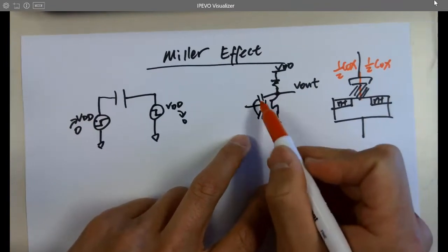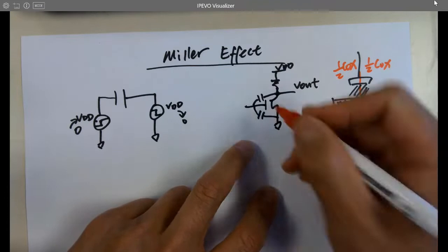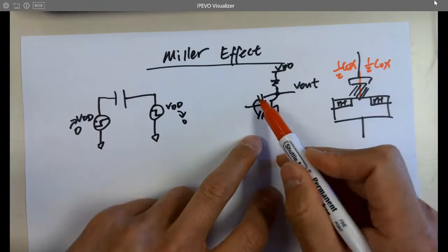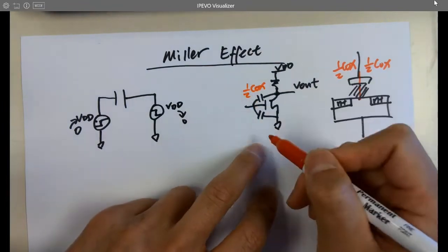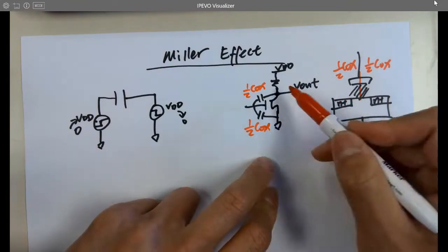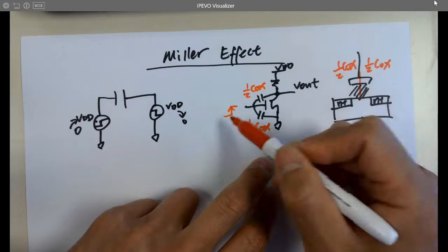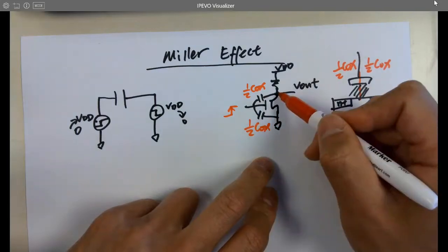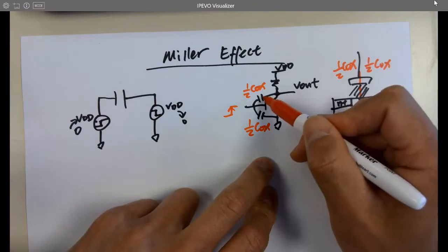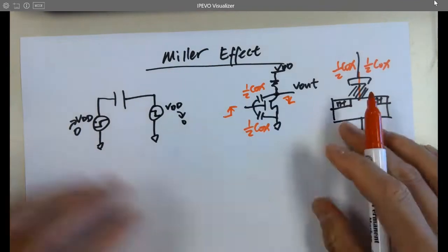There are no physical caps shorted to the gates. It's ridiculous, why do you do that, right? These are models. So what's the size of each capacitance? Half of Cox, physically, if nothing is charging and discharging it. But if you turn it on here, this part is going to discharge this point, which is the other side of this cap, at the same time. This gives you the Miller effect.